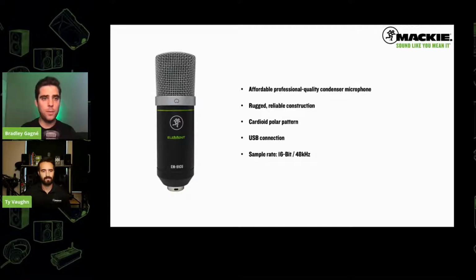You can adjust the input gain, raise up the level of your gain stage or your preamp basically through the computer settings. This is just a bare bones microphone, large diaphragm. The cardioid polar pattern is perfect for recording vocals or acoustic guitar. And the ease of use is really simple. I'm going to show you how to get it all set up. So let's check that out.